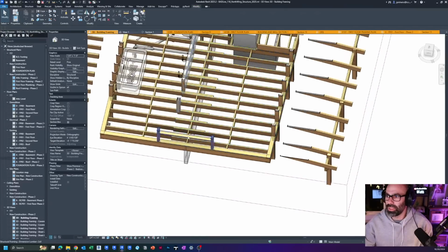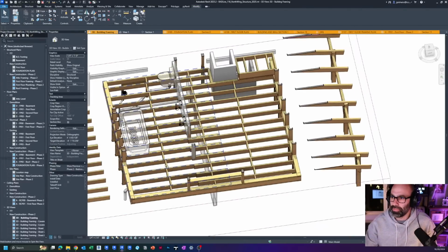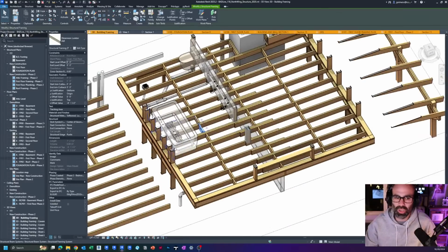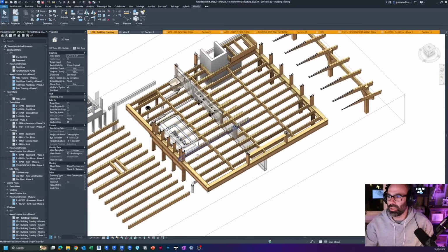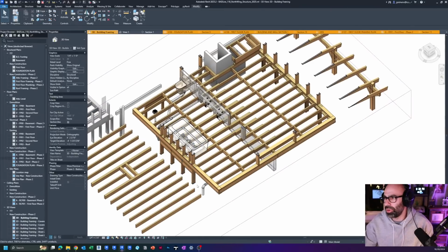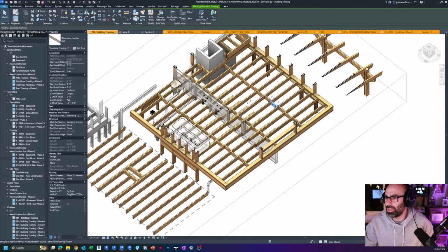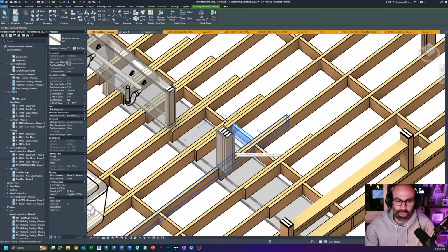So this is two beam systems because I have a bearing wall and they're overlapping and cantilevering through. And then the bridging, so this is one of those things where I'm showing it as 2x bridging. It probably will end up being some sort of metal strapping. I don't actually know exactly what we're going to do for bridging yet, but one of the things that I wanted to do was just show it, especially on the bearing wall, because that's something that I wanted there.